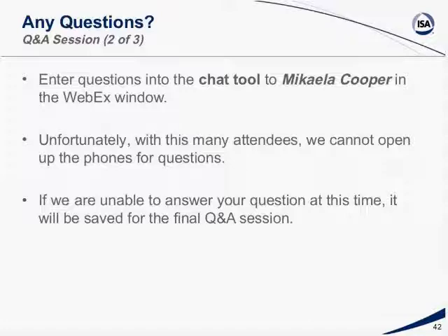We're going to talk about things you're going to do to improve the overall cycle. Typically speaking, you can expect to rationalize 50 tags a day, and there'll be multiple alarm parameters associated with each tag. That's just kind of a rough idea. But the other thing too is that when you're doing this, it's going to vary a lot by type of facility.